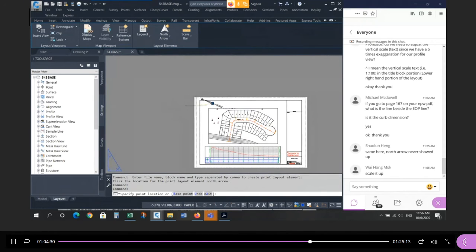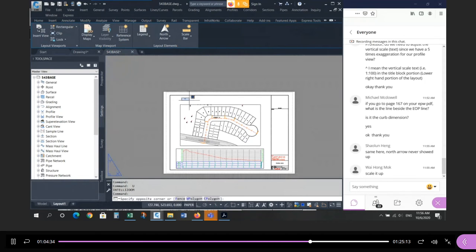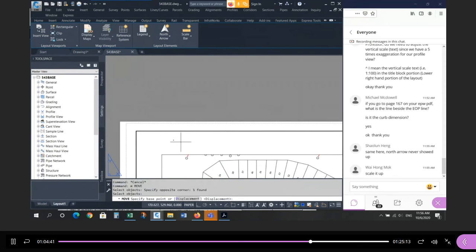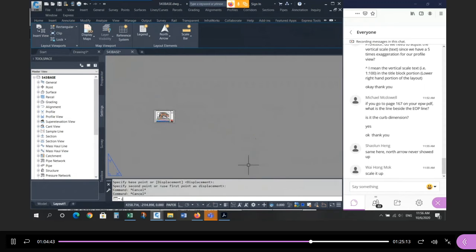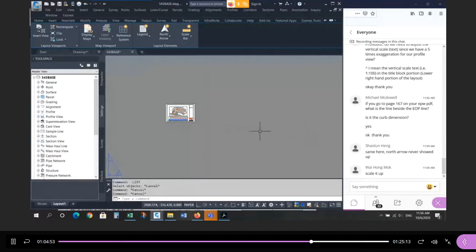Very, very small. So you need to click on it if you can find it and then change the scale by stretching it. Okay, if you don't see it, it's because it might be not in the frame, so it might be off here somewhere. So if I zoom extents, if you see that effect, it means it's out here somewhere. That may be the other problem. And the third issue is if it's on layer 0, which it should be by default.